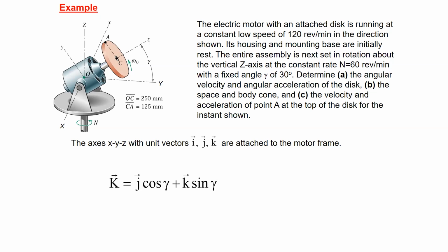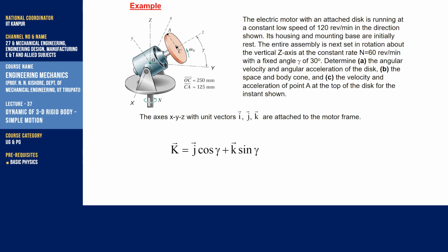So you can realize that the disc gets input from 2 angular velocities. One is the velocity about the vertical axis, and the other is the spin of the motor. Just like almost the same examples, you can call them omega 1 and omega 2. For the spin velocity, you should be able to convert from one coordinate system to another, taking care if the system itself is moving.